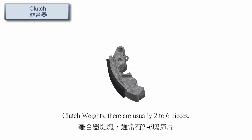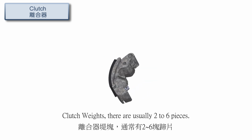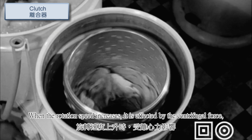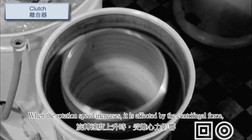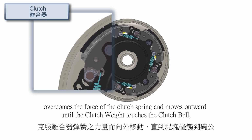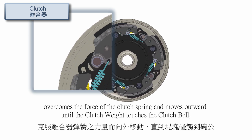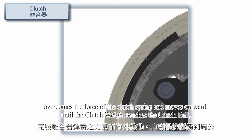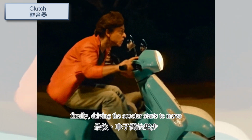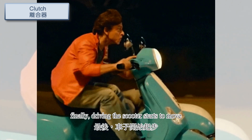Clutch weights, there are usually 2 to 6 pieces. When the rotation speed increases, they are affected by the centrifugal force, which overcomes the force of the clutch spring and moves outward until the clutch weight touches the clutch bell. Finally, driving the scooter starts to move.